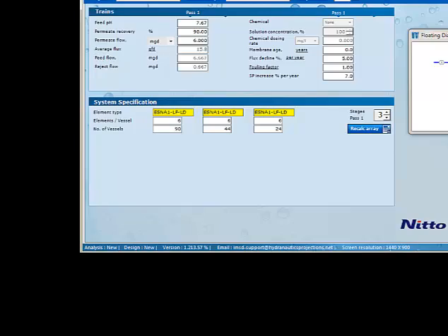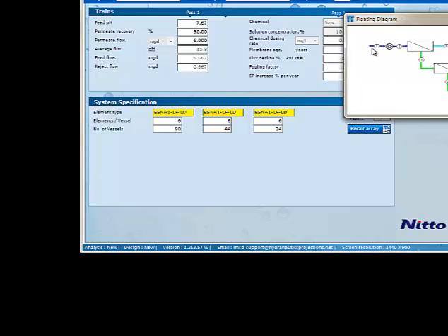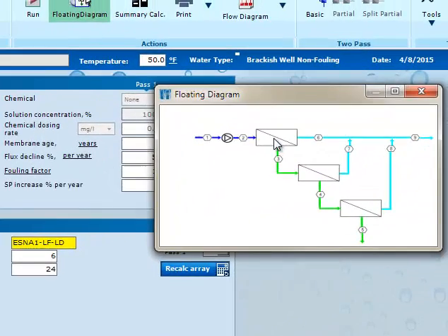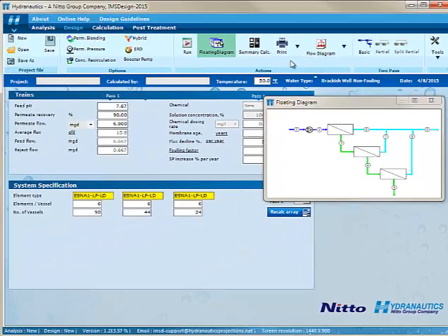You can see a flow diagram, so this would be the diagram of how this system works. So we got our permeate passes through clean, a retentate, they take the retentate, pass it in again, and then squeeze some more out of it on the third pass here. And this total that's at number 9 would be our 6 million gallons per day of that system.